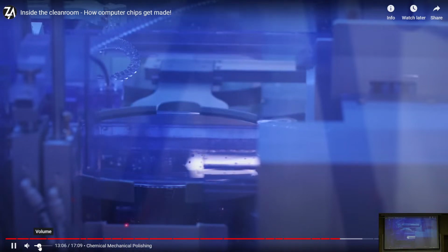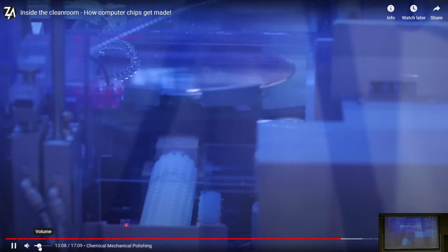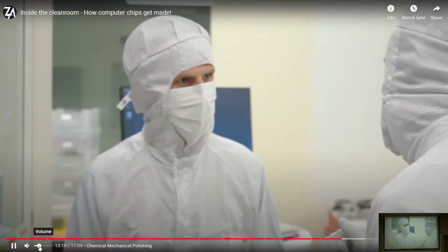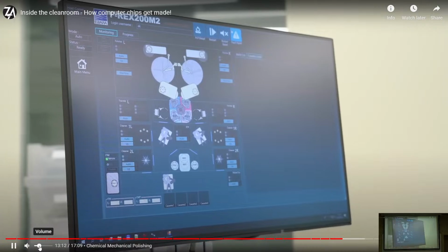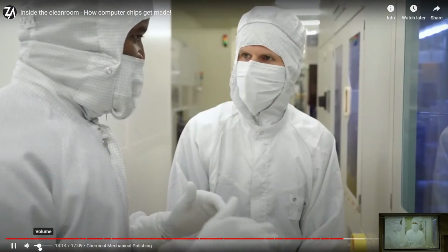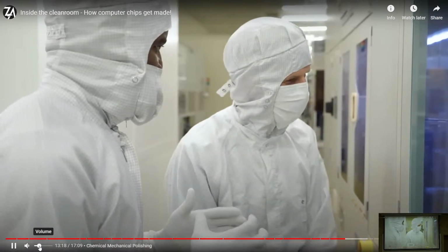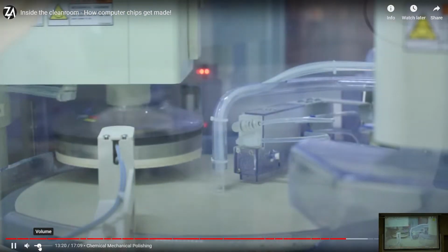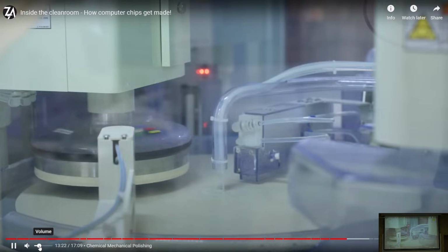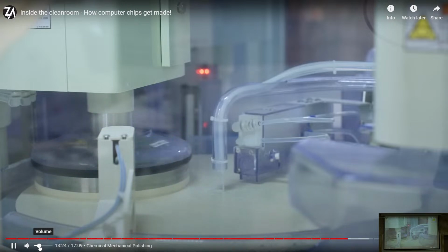So I'm just done with the process right now. But I can start the process if you want to see. Yeah, that would be amazing. Okay, I can start it. The warm-up wafer comes in twice, then the real wafer. Oh, so you have like a dummy wafer. Exactly. The dummy wafer comes first to check the process. Once everything is good, the real wafer can come. If the process is not good, you can abort it. It's like a safety. That's what we call it, the warm-up wafer.